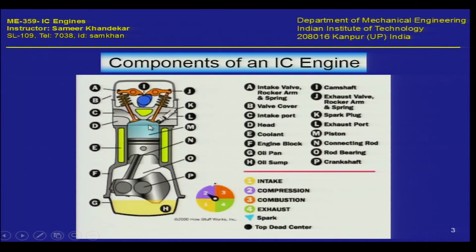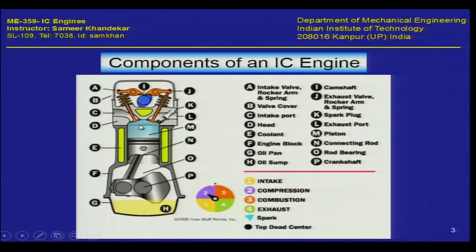And you can clearly see here the combustion chamber, and the design of this combustion chamber will also affect the way the heat is released. For example, the flame propagates inside this combustion chamber, the way the combustion products are formed, and the dynamic transport processes which occur, the amount of turbulence which is created inside this combustion chamber, the amount of swirl motion which is created inside this chamber. So the velocity field which is generated inside this combustion chamber is actually dependent on the geometry, and therefore this also is an important parameter, as we will see as we go along.